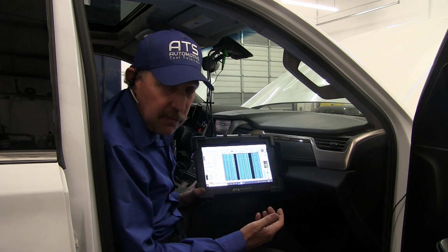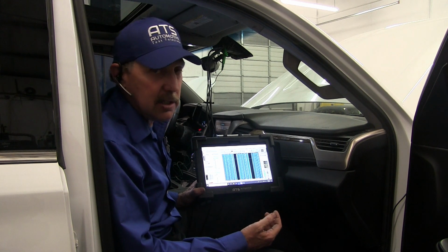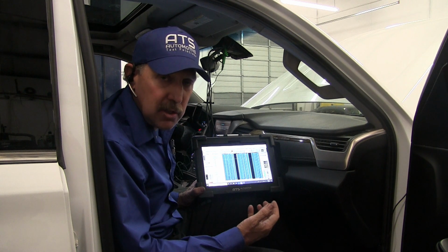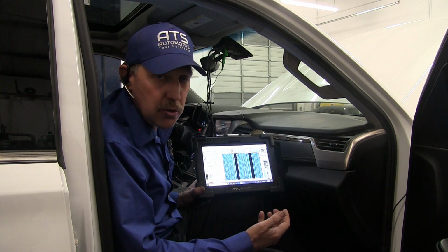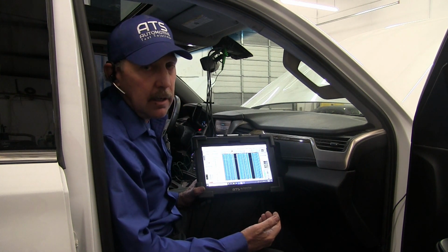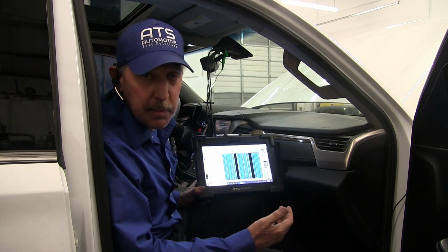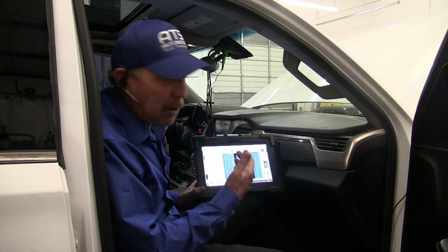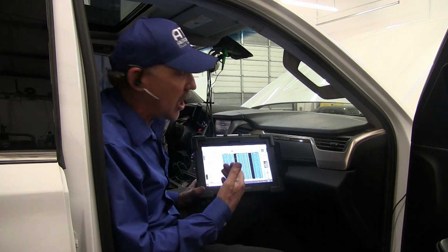Now what's really confusing about this is you use a factory scan tool and you think that data is going to be great. But the problem is, even with the GM system, it's telling me that those codes are history codes, that those codes have passed and failed. Those codes could have never passed. The wire's broken. The wire's been broken since we got here. The wire was broken before. That's why we're working on the car, because it has a broken wire for the GM LAN.